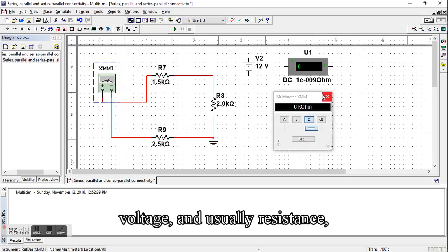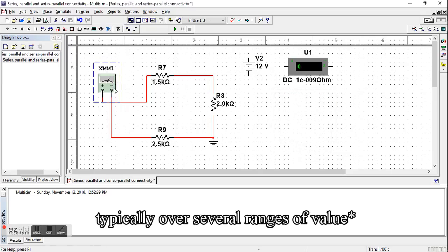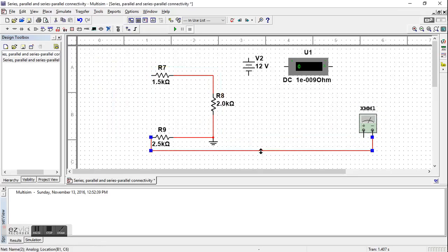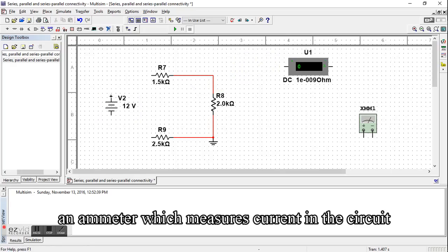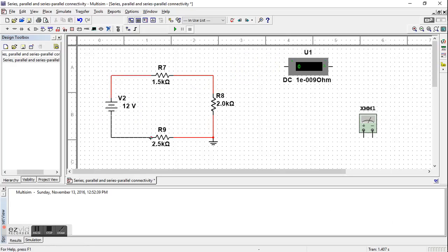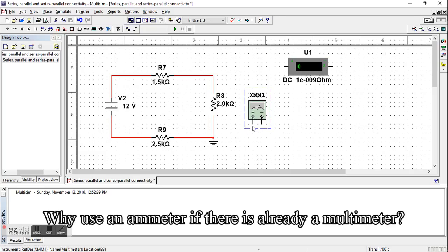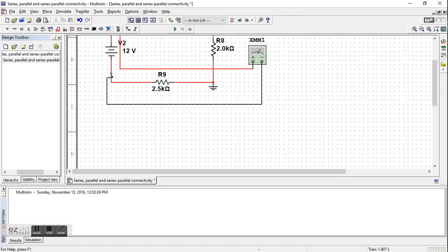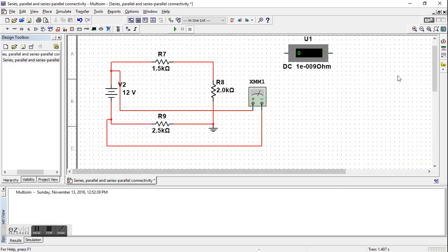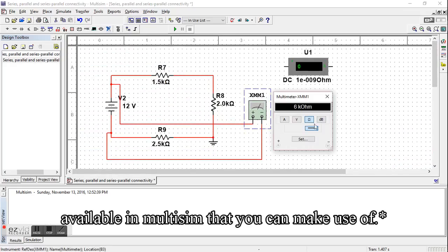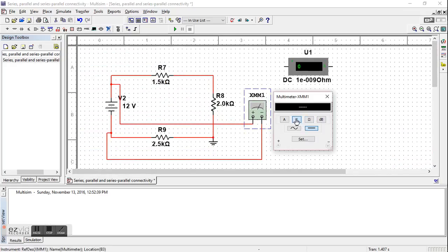Next part, I'm going to show you how to get the total volts. This time we need a DC power source of 12 volts. Connect this multi-tester to the positive side and this end to the negative side. And then in volts, the tester, run it, shows 12 volts.